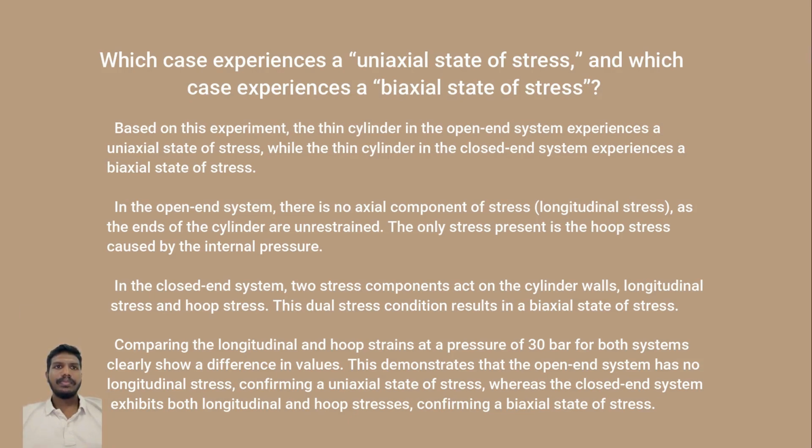In summary, open-ended thin cylinders are unrestrained at the ends, leading to a uniaxial stress state with only hoop stress. Closed-ended thin cylinders have sealed ends, resulting in a biaxial stress state with both hoop and longitudinal stresses. This comparison highlights how the cylinder's configuration significantly affects its stress behavior under pressure.